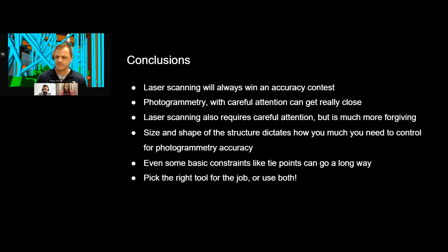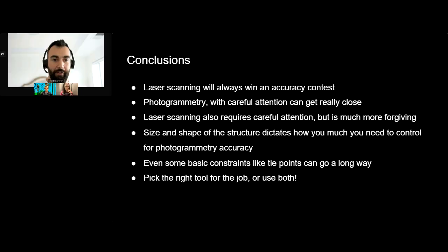Okay, we'll move on. How do you handle ground control points, and what do you recommend for GCPs on larger surveys? There's a lot to unpack with how to put controls and how to measure those controls. So the traditional way is GPS, but as you saw on the bridge example there, the question is how do you get GPS measurements for controls there?